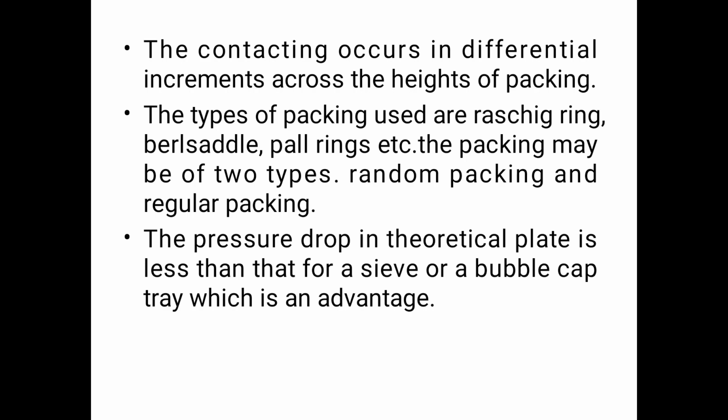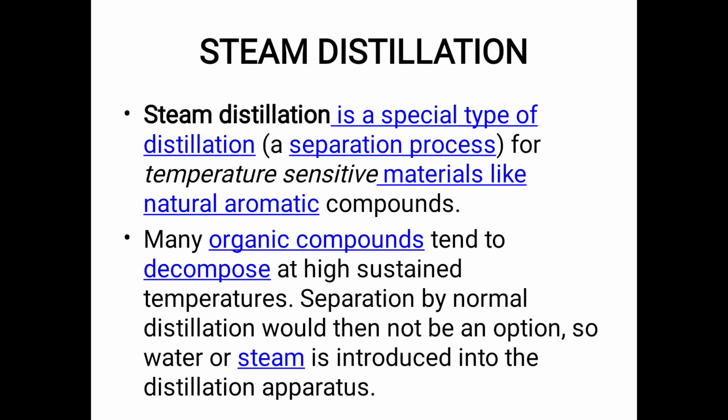The packing may be of two types: one is random, another one is regular. The pressure drop per theoretical plate is less than that for a sieve or bubble cap tray, which is an advantage. Then we will move on to simple distillation. Sorry, it's steam distillation. Steam distillation is a special type of distillation.